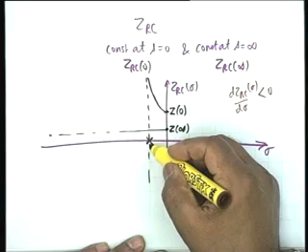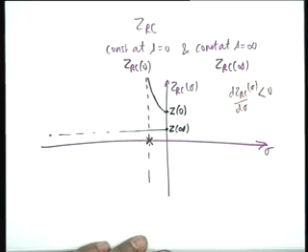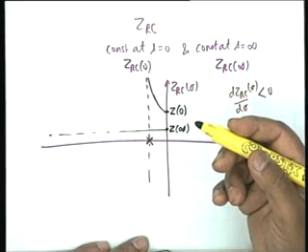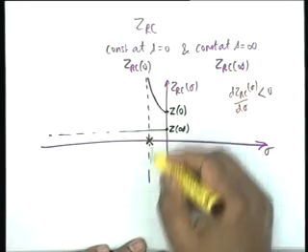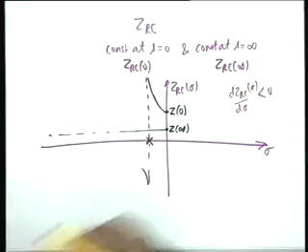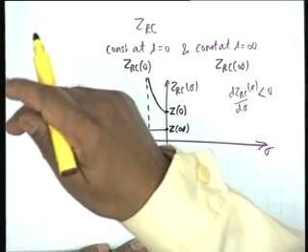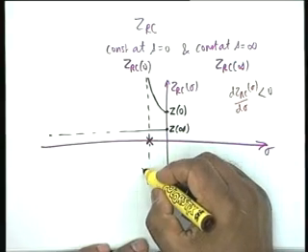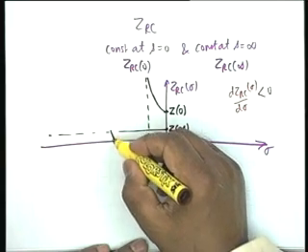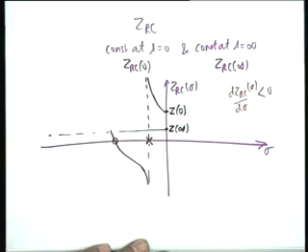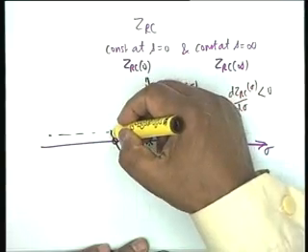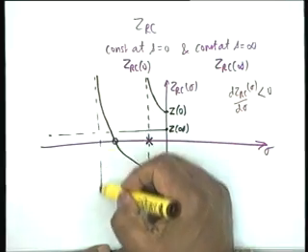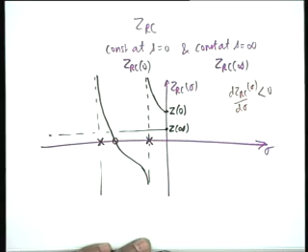If it goes to infinity, obviously there must be a pole there. You know that at a pole the function changes sign, and therefore after the pole it must rise from here. It must rise. It cannot fall. From minus infinity it must rise. So the next critical frequency must be a 0. And then it should continue to rise, so the next critical frequency must be a pole.